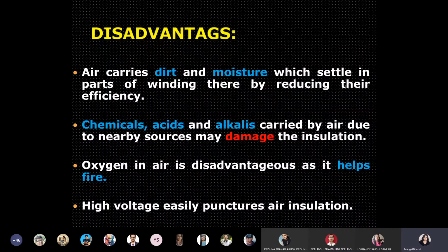Now you will ask me how transmission lines are used. Even if they are carrying very high voltage, you just see how much spacing is used. Spacing between two conductors is very large. And if you want to use air in our devices, then your device size will be so bulky. For a transmission line, it's okay, it's used in the atmosphere. There is no space criteria. But in the devices, there is a space criteria, then its volume. So that is the thing you have to understand.